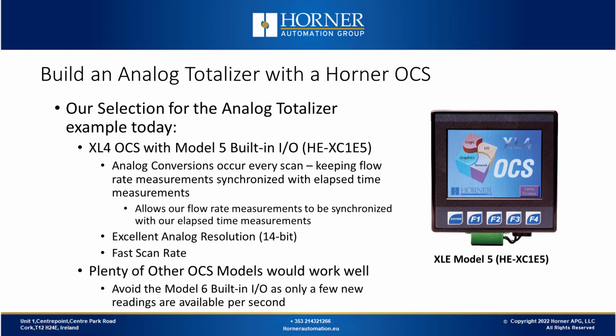Also, the Model 5 built-in I/O has 14-bit resolution, and the XL4 and the XL4 Prime both have a fast scan rate. Now, plenty of other OCS models would work well. If you have an application where the accuracy isn't as critical, then a micro OCS with its 12-bit built-in analog